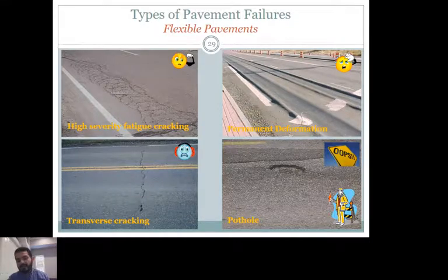Potholes, everyone knows them. It's a hole in the pavement where you can see the pavement is sinking, or some of the pieces are leaving the structure. This happens mainly on the sides of the roadways because when we pave, the paver has a shoulder, or wings. So when we pave, sometimes most of the paving weight of that paver is on the main structure, and the outer size of the lanes are not highly compacted.